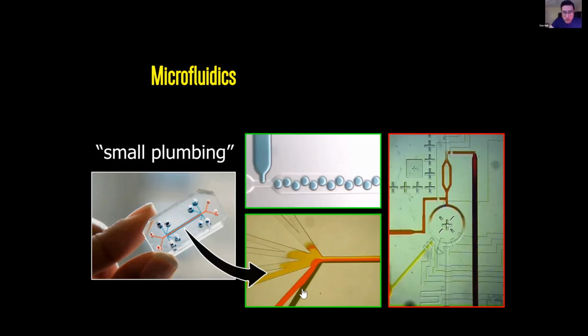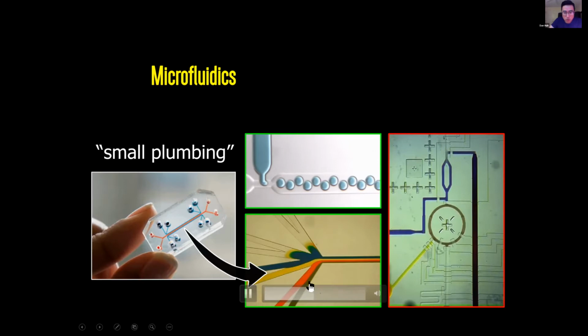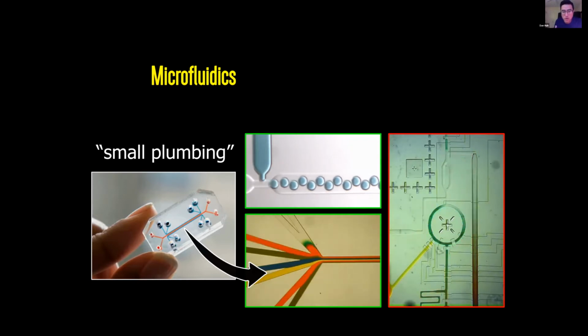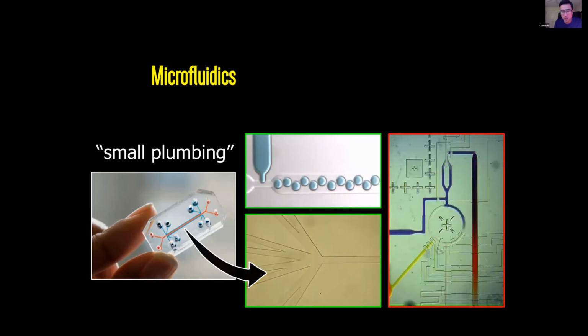And another example, you can inject multiple types of liquids into a common channel and have these different liquids flowing right next to each other without any convective or turbulent mixing. Using this technique called the multiple laminar stream technique or laminar flow patterning technique, you can develop very novel assays for biomedical applications. Again, it'd be a stretch to cover all these different techniques and technologies, microfluidic platforms in this short introduction.